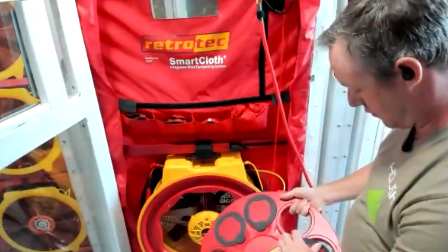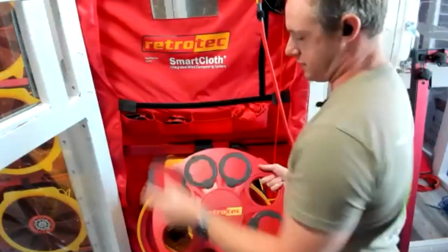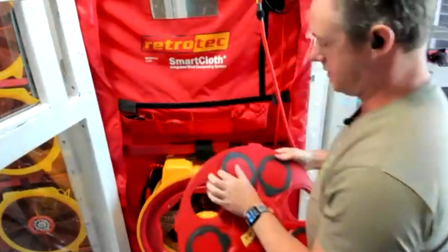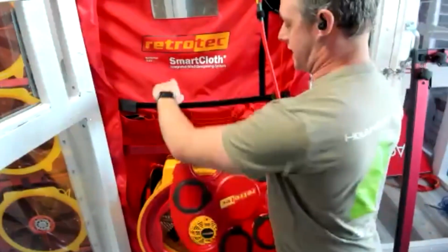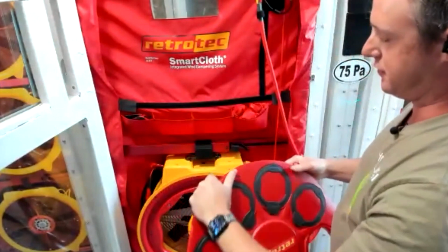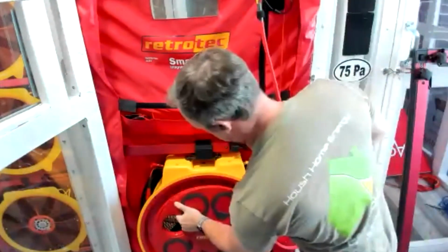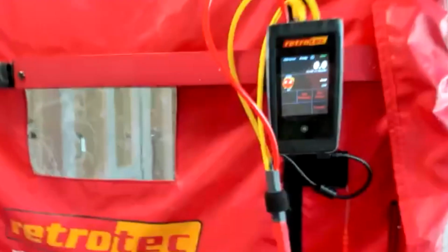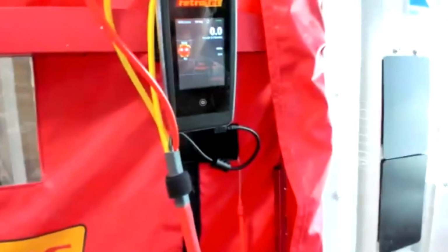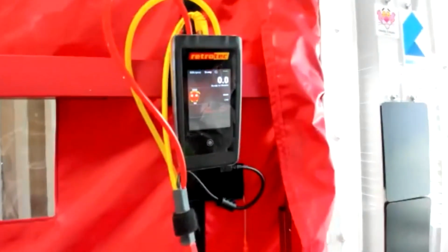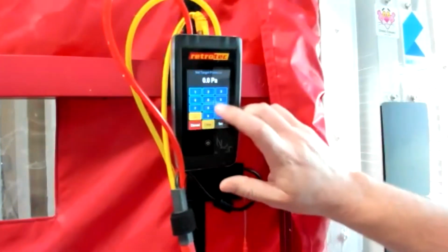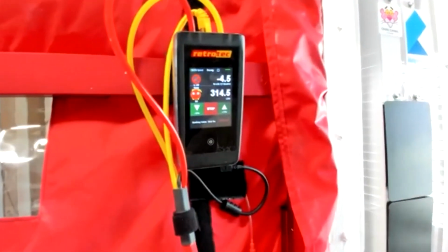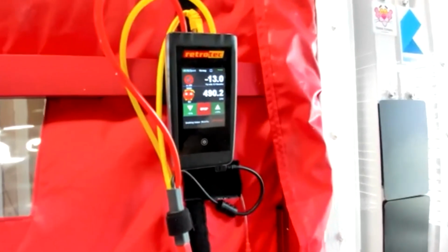So now we're going to have that hole opening on the inlet side of the fan too small. And this is how the gauge lets you know where you need to go. So if it's too open, it gives you those 2 dashes on channel B. We're on B2 here. Do our set pressure to 50. Really hear that fan starting to crank on down.